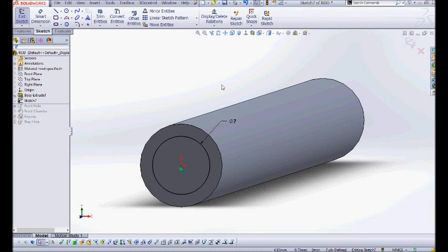The first thing we're going to do is change the size. Make sure you've set it to type drill sizes. One person had theirs set to dowel hole, so make sure you have it set to drill size. Once you've got the size changed, you're going to go over to positions. You're going to right click, go select. We want to add a relationship between the center point and the origin.